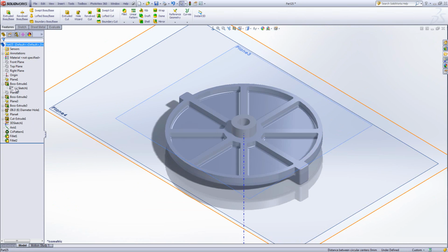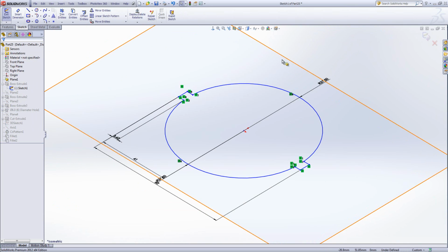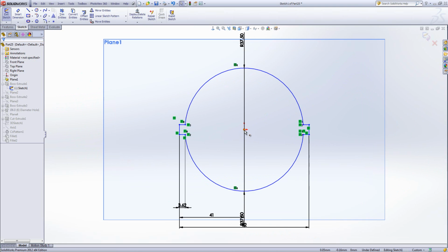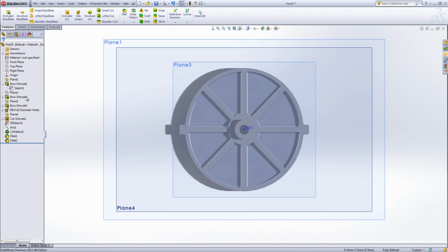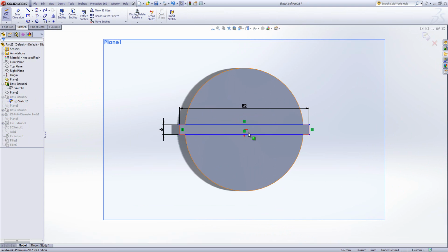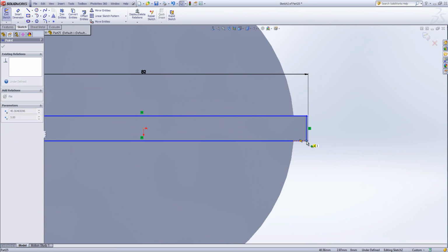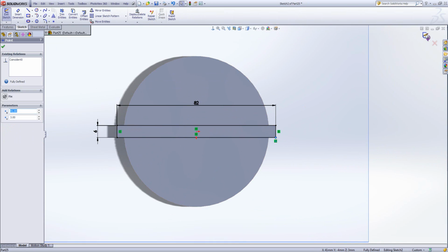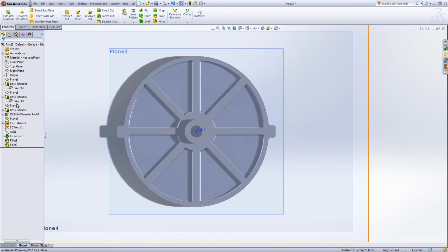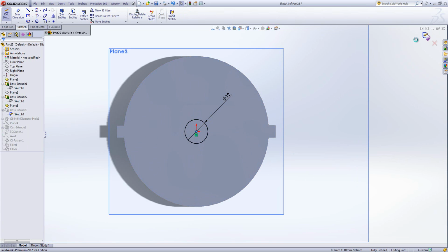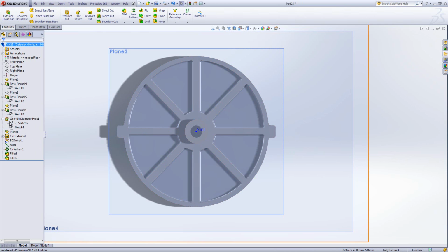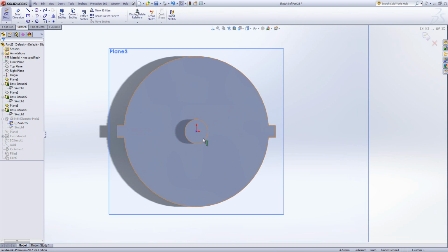So in terms of those sketches, it does become a lot quicker for actually defining them in position. You see with an item like this one, it just needs hooking into something like the origin point. Or for sketches further down the design, like this one here, well, we just need some kind of placement onto, say, a corner point of the design. You need just simple relationships just adding in, just to hold the items in place in relationship to the rest of the model.